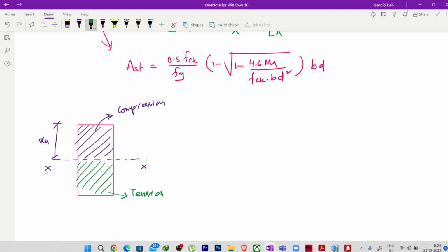Okay, the position of this neutral axis, if it is at such a position where the concrete at the top and the area where we have the reinforcement bars are both reaching their ultimate stress limit simultaneously, in this case we will call this particular section our balanced section.